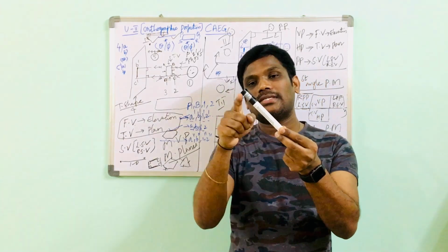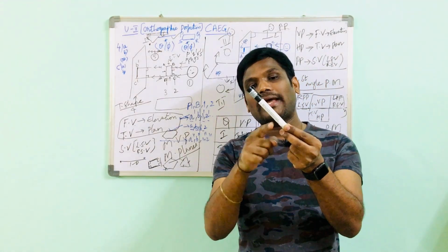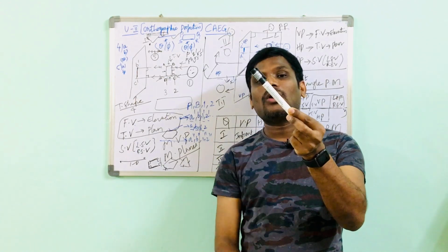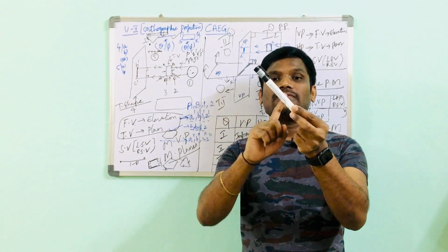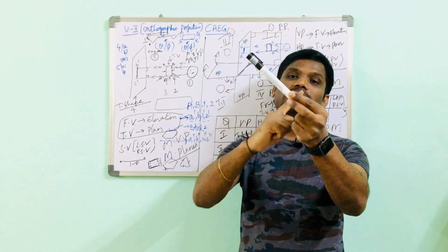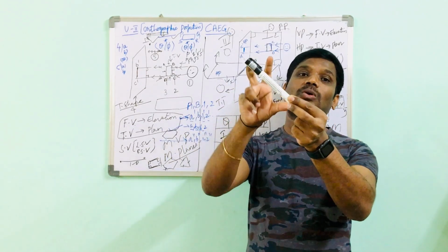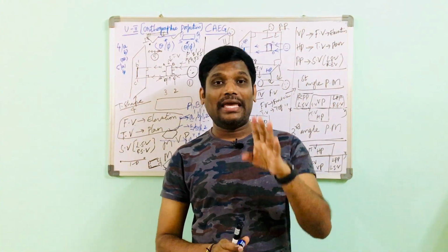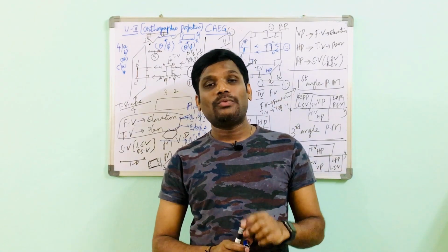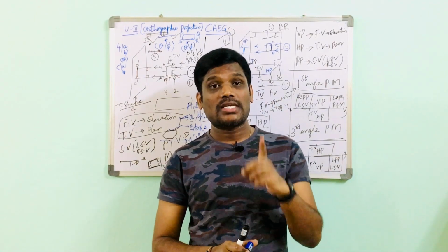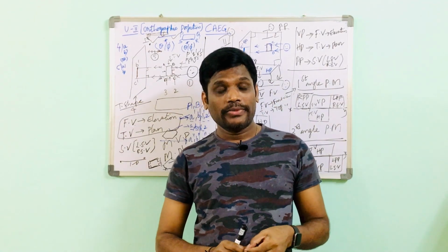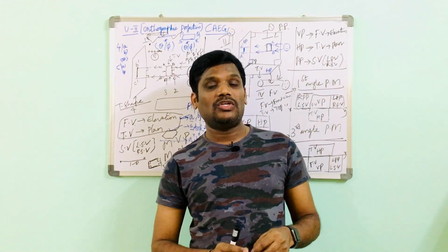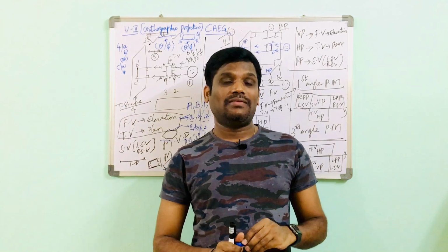But how is this line to the horizontal plane? This line is inclined. When I draw a set of lines from this inclined line, all are of different heights. Whereas when I drop a set of lines from this line to the board, all the lines are equidistant. I forgot one point telling you: in Unit 1, they may ask you to divide a line into 5 equal divisions using the division of line method. And they may ask you to divide a circle into 12 equal divisions or 8 equal divisions, dear students. Please work out that also.